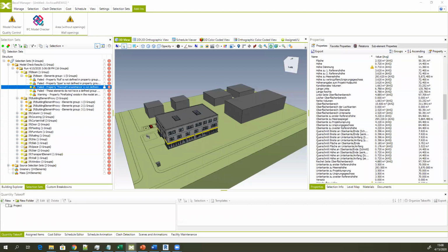What are the differences between categories and the rooms? Well, categories are different types of BIM model elements, and the rooms are just a specific type within that. So the rooms are a specific type of the spaces, IFC space. This is the way how Revit actually handles different types. So Revit has the spaces and the rooms, but within the IFC, these are IFC spaces, and you can additionally segregate these into different categories.